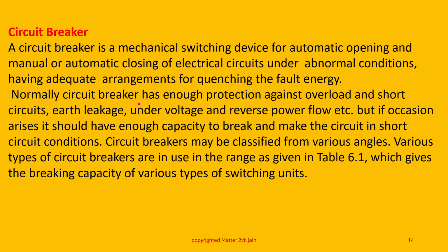Normally, a circuit breaker has enough protection against overload, short circuit, earth leakage, under voltage, and reverse power flow. But if occasion arises, it should have enough capacity to break and make the circuit in short circuit conditions. Circuit breakers may be classified from various angles as shown in the table, which gives the breaking capacity of various types of switching units.